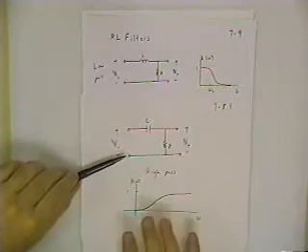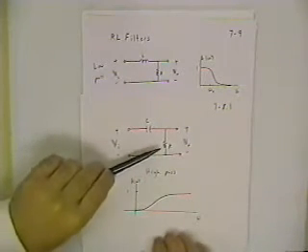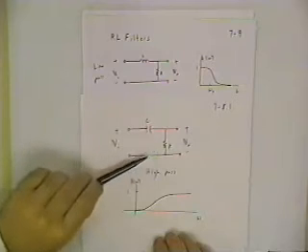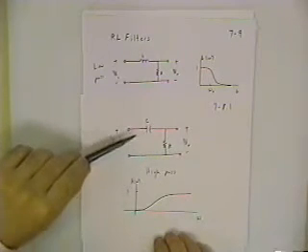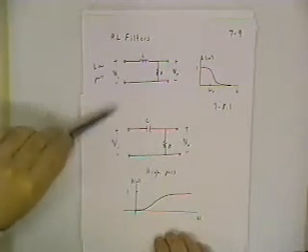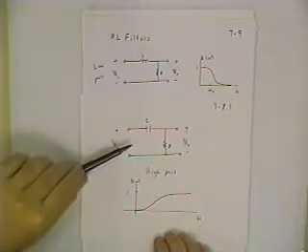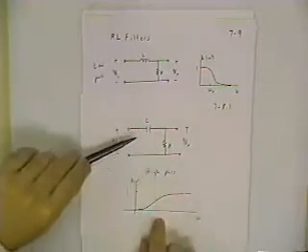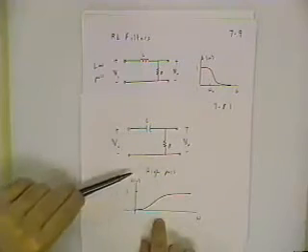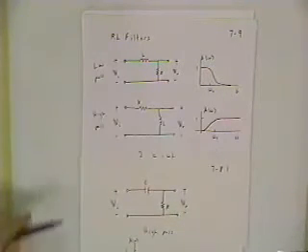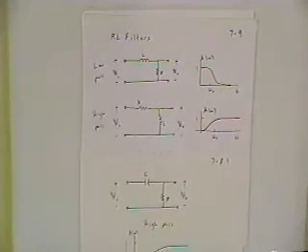And now I know all the other three, because I know if I switch the R and C, I get a low pass RC. If I replace the capacitor with an inductor, I get a low pass RL. And if I replace and then switch so that there's a resistor up here and an inductor, then that's my high pass RL, just like I showed you here. So for these first order filters, all you really have to do is apply the voltage divider to the first one and then remember all the others just by the arguments I just made.